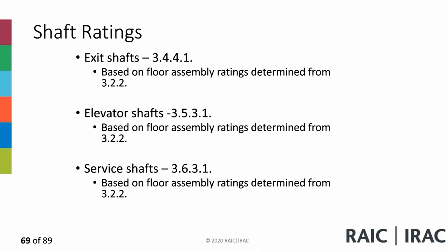Okay, so we know that the fire resistance rating of the fire separation need not be more than 2 hours. Every exit shall be separated from the remainder of the building by a fire separation having a fire resistance rating not less than that required by subsection 3.2.2. So 3.2.2 dictates the floor ratings, and 3.2.2 dictates the rating for your exit shafts.